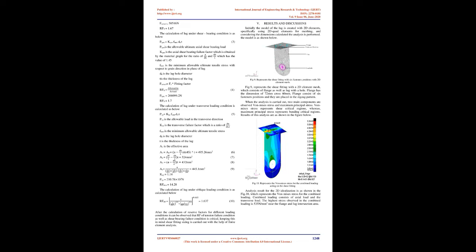Tensile reserve factor RFT equals allowable by actual, equation 2. Ptux equals 266250.24 N. Factual equals FZ asterisk fitting factor. Factual equals 58516 N. RFT equals 1.67.